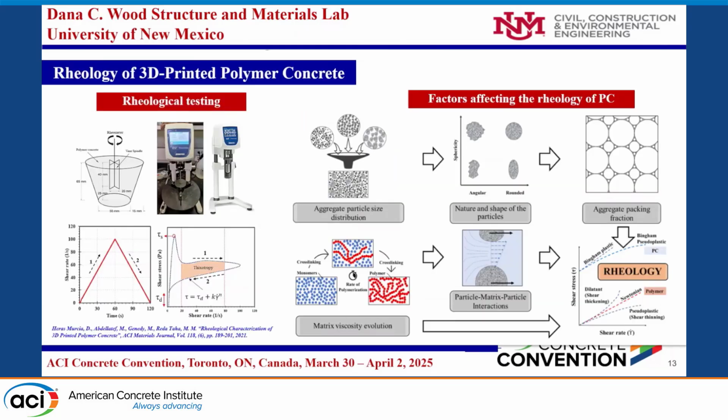Of course, that's all happening because of the rheological behavior of the polymer concrete. The rheological behavior of the polymer concrete highly depends on the aggregate and the polymer type and content. And the big picture is the polymer and aggregate interaction together. Polymers by themselves have a Newtonian behavior with zero thixotropy and zero initial shear stress. However, once we start adding aggregate, we start to see an initial